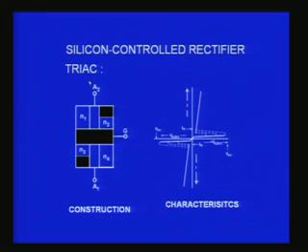You see on the screen, this is a TRIAC, triode AC. Again, you have the same two anodes A1 and A2. There is no cathode, because you know the signal can be this side positive, this side negative, and this side positive, this side negative when the AC changes, and therefore both are called A1 and A2 anodes, and you have a gate. You have a single gate only. If I use two SCRs, I will have two gates which have to be controlled. In the TRIAC, it is cleverly designed by controlling the layers and all that. Therefore, you find only one gate. By controlling it, you would find you can control both halves of the AC signal, make it conduct at any desired angle.